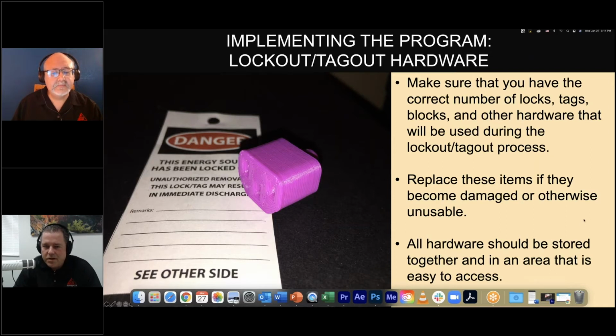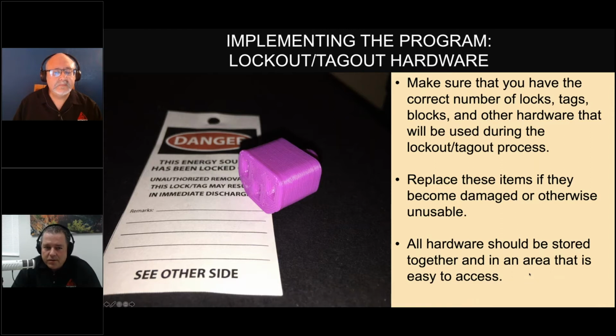Another thing that we see all the time is zip ties. Zip ties are not good lockout tagout equipment. They're not compliant. If you use zip ties, you could be fined for that. And they're easy to remove and replace. Someone could remove it and replace it and you'd never know. That's probably one of the reasons why it's not a good idea to use them.